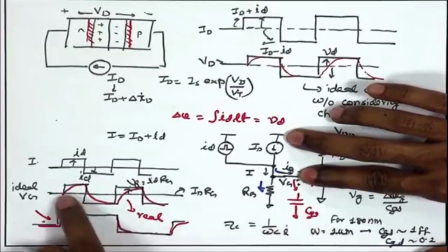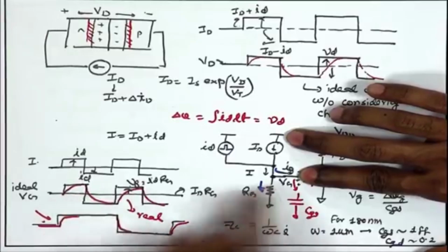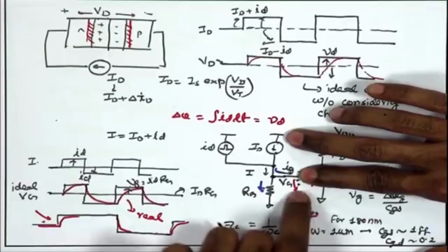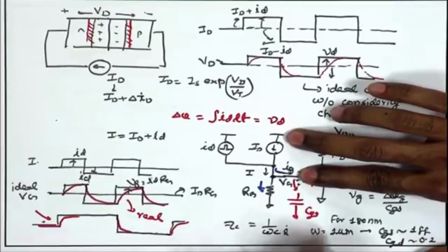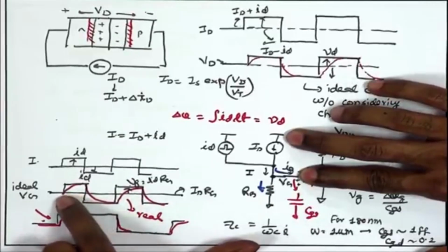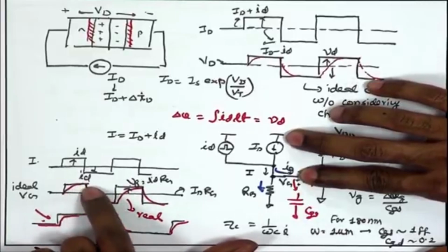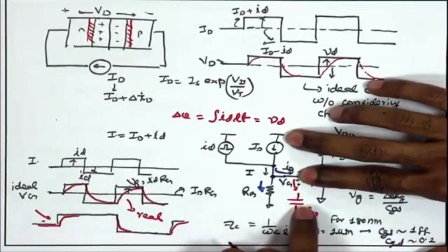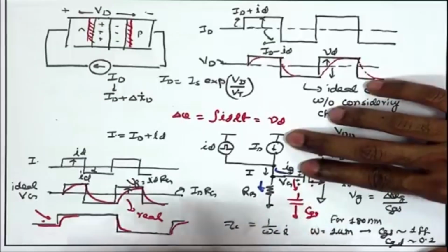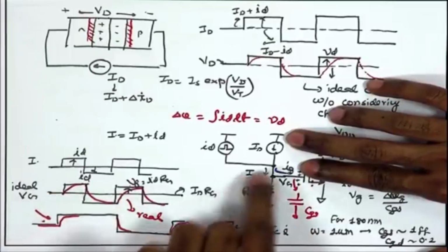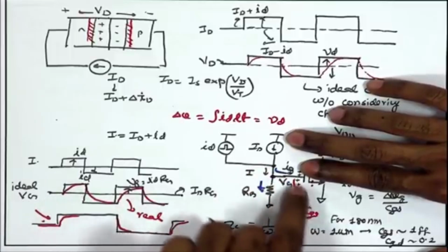So, you will take some finite amount of time to increase the voltage across this capacitor by integrating the small current flowing into the capacitor for finite duration, then only the voltage of the capacitor will gradually rise and reach the final value. If the CGS is larger and larger, if this effective capacitance between this point and ground is larger and larger, you are going to take more and more time to integrate the current and cause the same